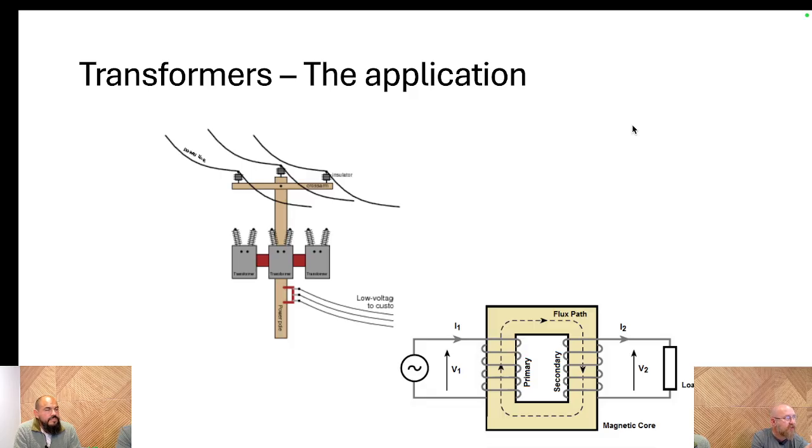So it's far easier to just deal with all of these little windings to transfer. We step up the power to go to those transmission lines, and we step it down when we get to your house. And those transformers still have rules applied to them, right? We can't draw infinite current on each one of these things, because all of those individual wires on them will melt.